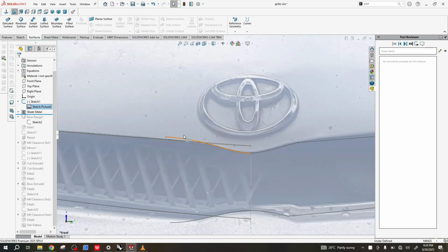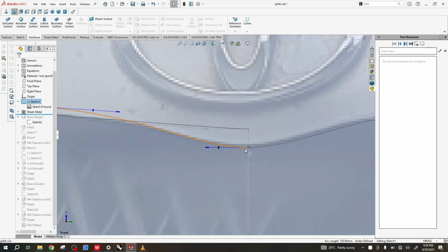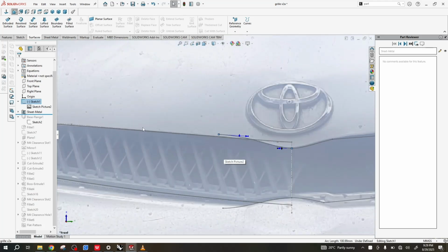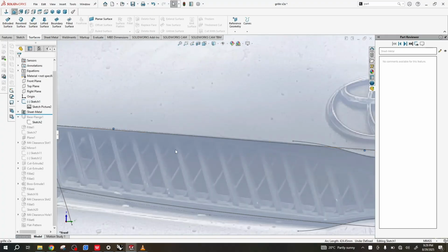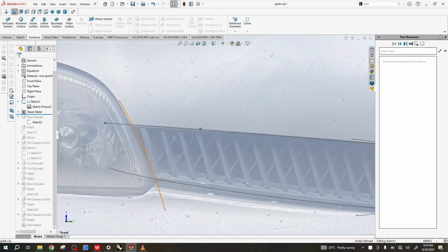And as you can see, I'm not just using one continuous spline. You can just break it off and then they can interact. This is one swoop, and where they meet the center line, make sure they're actually horizontal. You really need that, because when you reflect it onto the other side, you don't want a bump where they meet. You need to make sure that it is tangent to the other side, so that the transition is quite smooth. As you can see, this is one spline, this is another spline, and then there's another spline that swoops from this side.